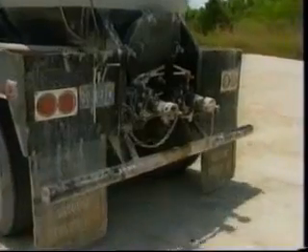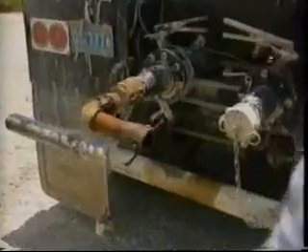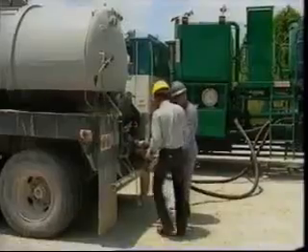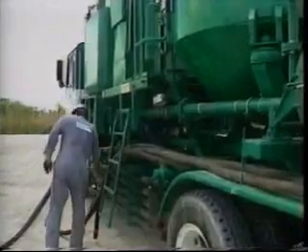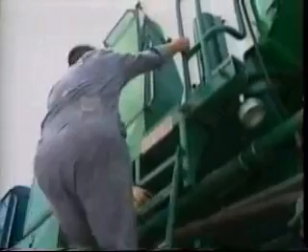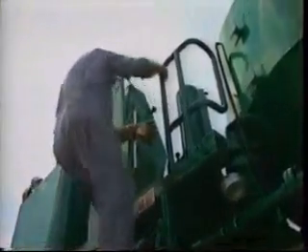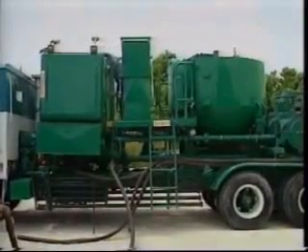Any water that will be used as a pad or flush fluid should be tested for chemical composition and compatibility with the acid and formation fluid. Fluid and equipment cleanliness is extremely important in matrix acidizing. The tanks should be cleaned before filling them with either acid or water. Small amounts of debris can cause considerable damage during an acid job.